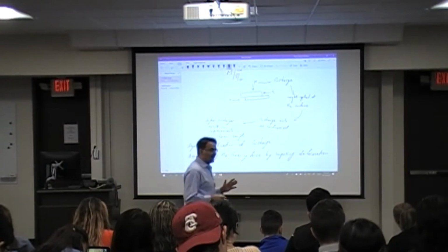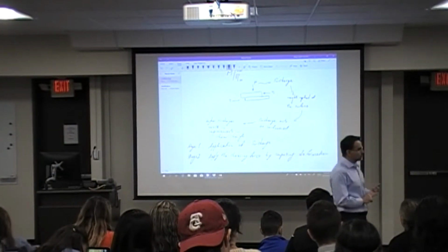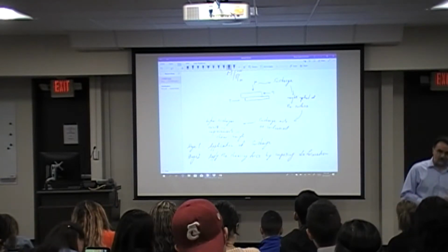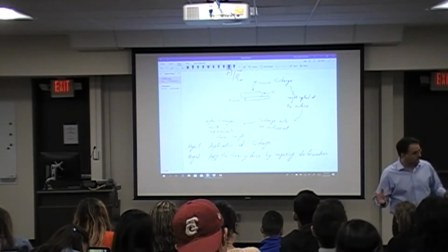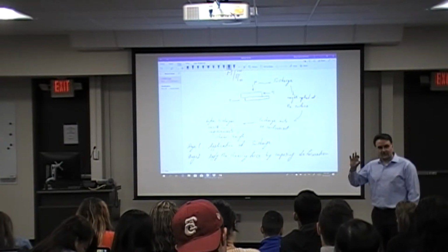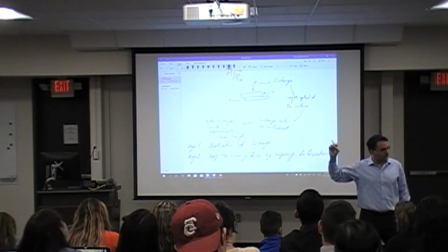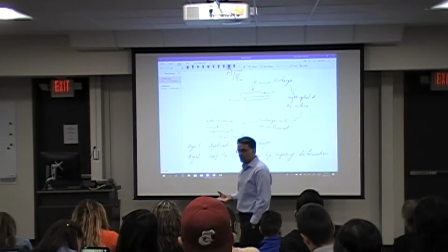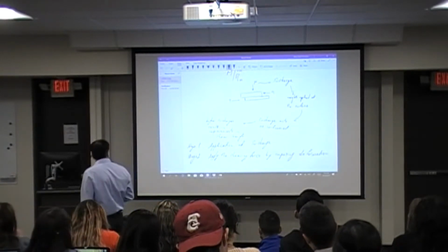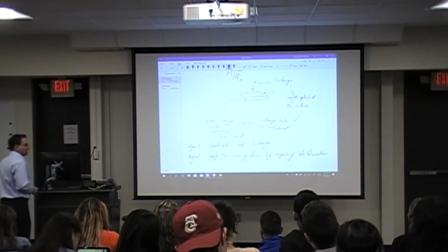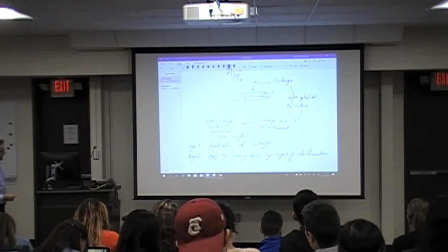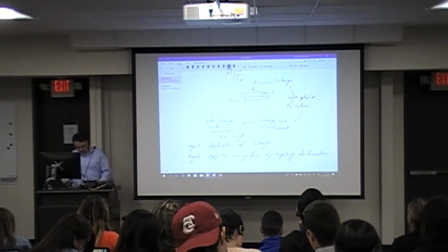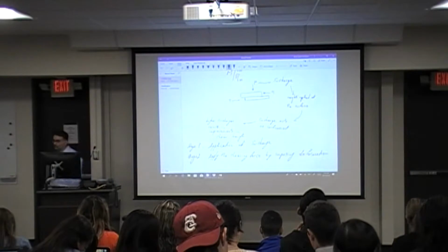So from this point on, any type of test that we talk about, we need to make sure that the material fails, right? You need to make sure that the magnitude of the stresses are high enough that it results in the failure of the system, because we are interested in determining points along the failure envelope. And any point along the failure envelope represents failed material, right? All right, so we have two stages of loading. Stage one, application of the surcharge. Stage two, application of the shearing force. And once you get those two values, you can simply calculate the normal stress and shear stress.